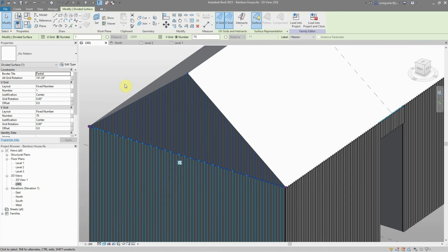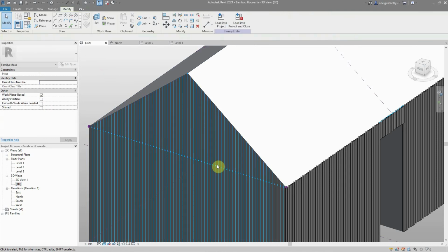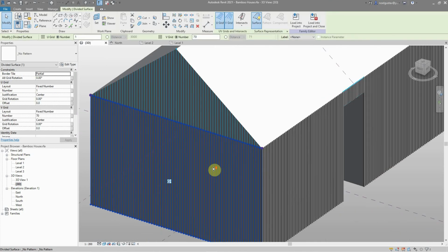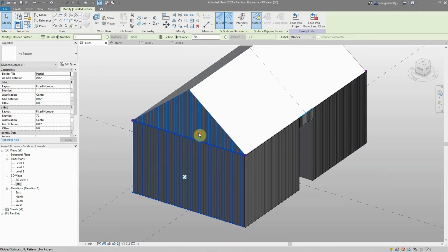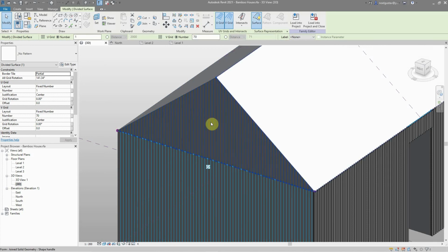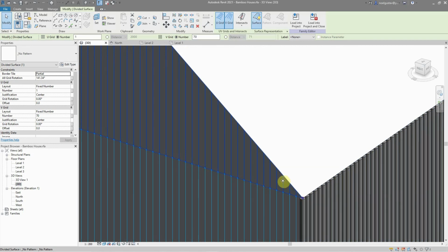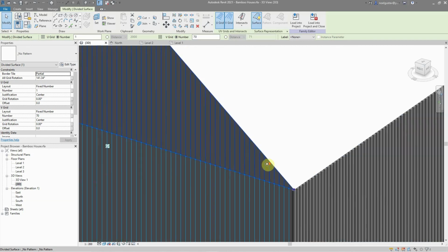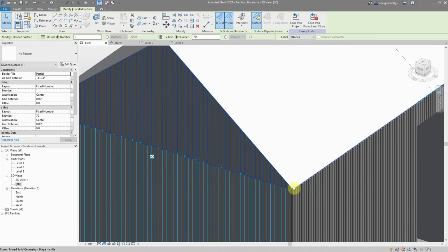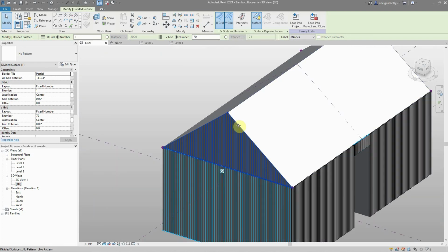Now after thinking about it, I think the best way to approach it could be to also add some horizontal grid lines, so that whenever they intersect, they will usually make a node. With that in mind, hoping that we can create as many nodes as possible along the diagonal lines, I'm just going to add, say, 50 of them.